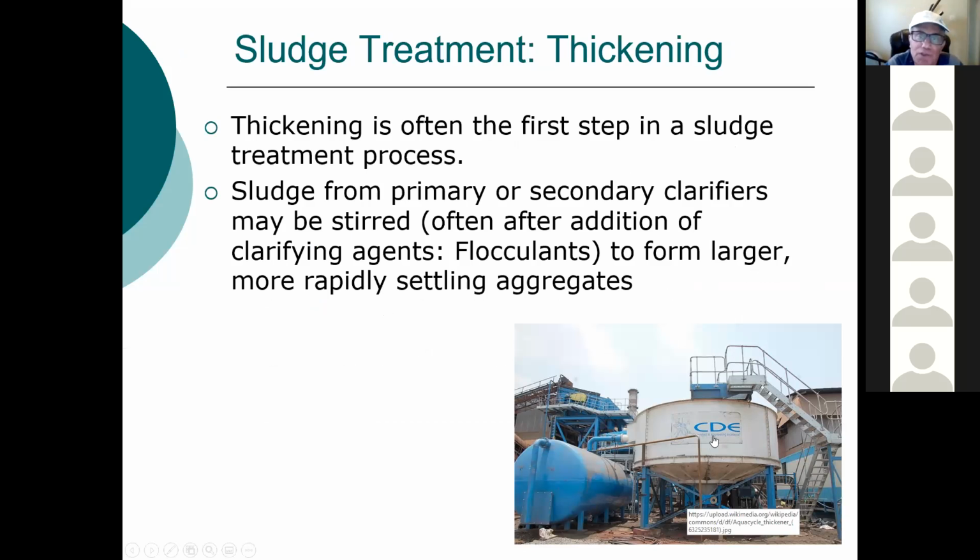Different ways, gravity thickening. If needed, you can add flocculants to them, such as alum, let them flocculate and bring together, either using these tanks, exactly as you did with flocculation. You need to stir them as well, or flotation.